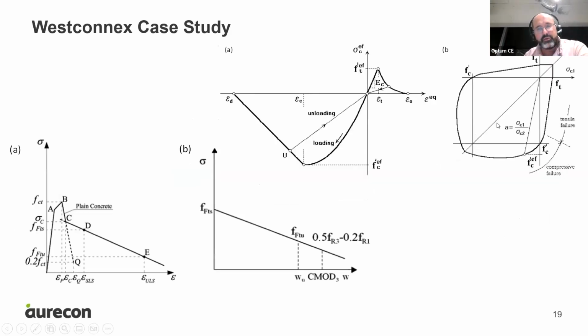Here's a very quick snapshot of our constitutive model. It's a simplified version. We're just showing here in the middle, at the top, letter A, the left-hand side, and upside down, is the compressive region. The right-hand side will be the tension. That's for plain concrete. So what we did in our modeling exercise, we replaced that tension component by the behavior of fiber-reinforced concrete, which is shown on the bottom left chart here, the A on the bottom left-hand side.